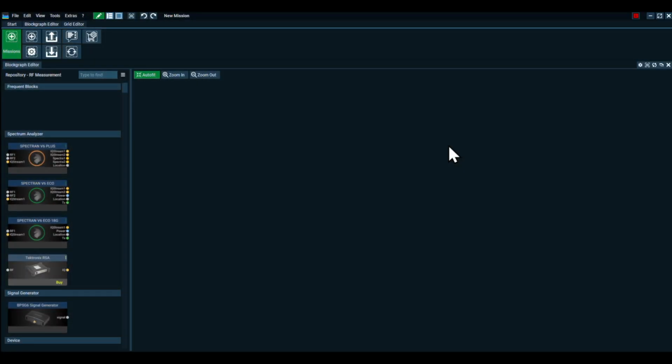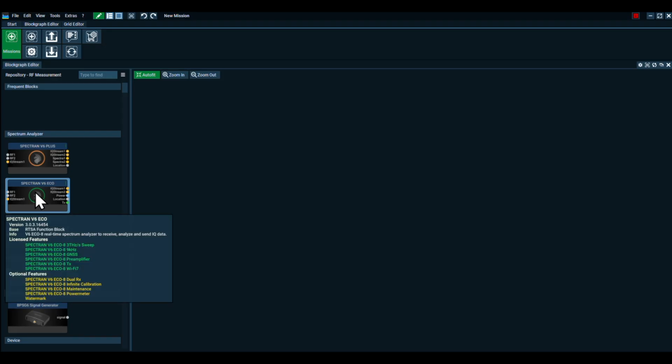In this video, we demonstrate how to measure the displayed average noise level, or DANL, with the Spectran V6 Eco. To begin, a preamplifier is installed in the V6 Eco unit. That is important for achieving the best performance.